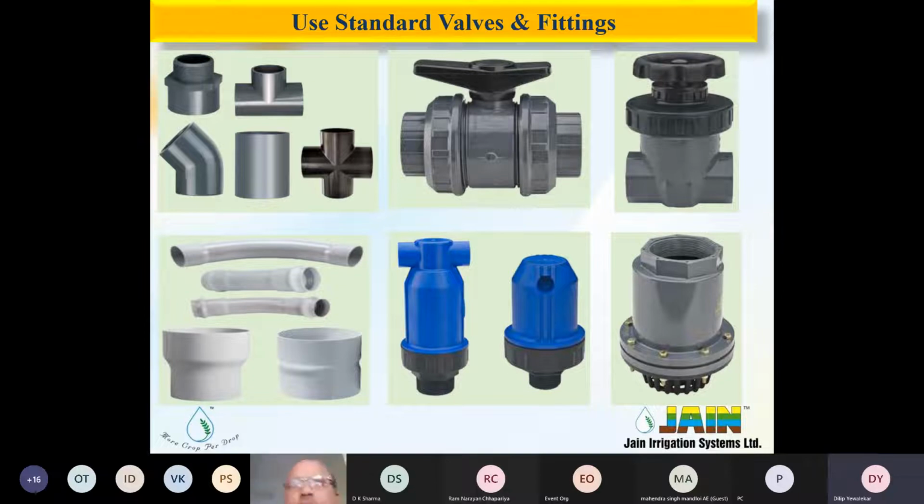And this plastic valve does not corrode. It has more advantages than the metal valve. You can replace it, you can repair it. It is very simple to operate, simple to install, and cheaper than a metal valve. And there is no theft. It does not have resale value, so the question of theft is not there with plastic.